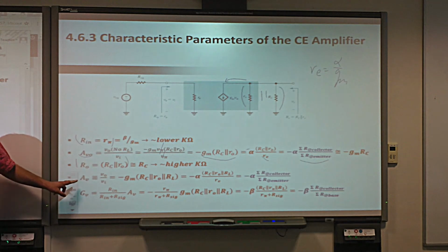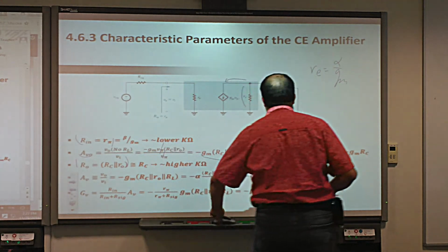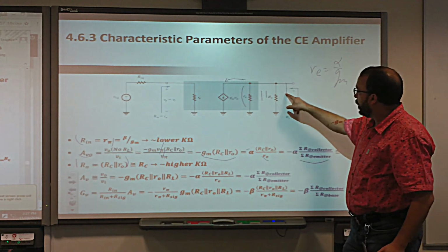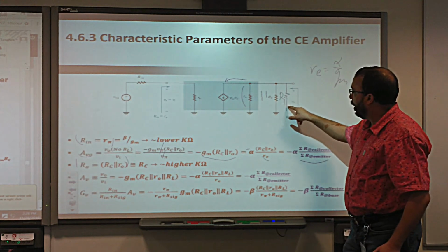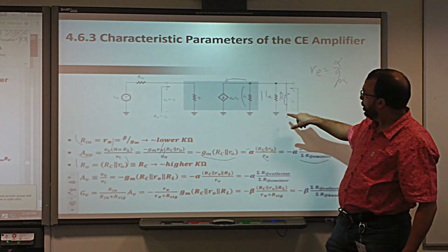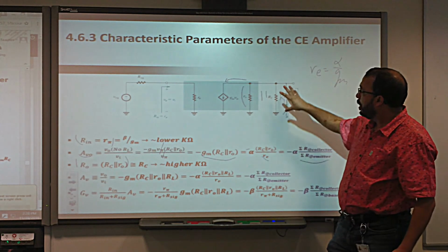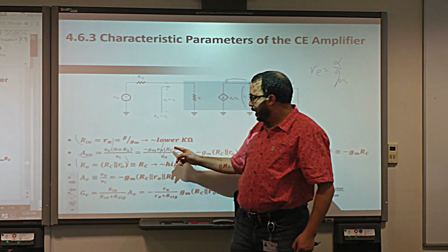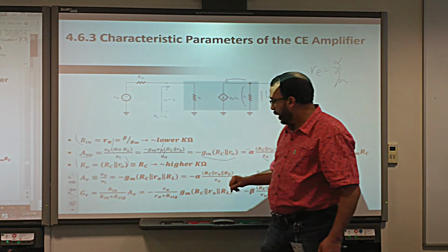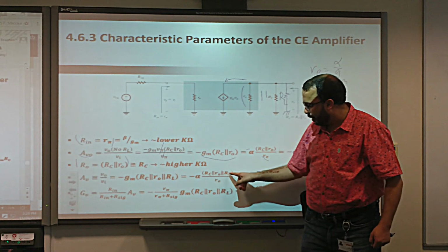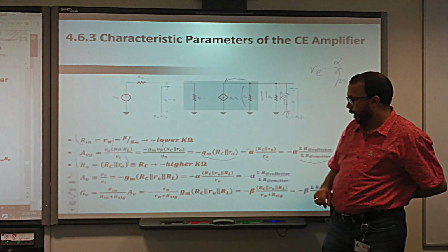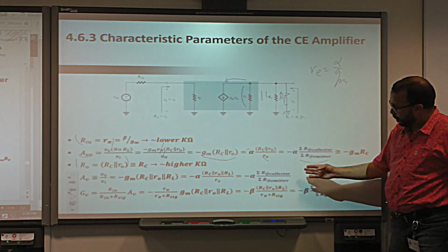Now, for the voltage gain, that means RL is included. The same thing, and it's very easy to calculate it, actually, because here, instead of RC, I will have RC also in parallel with RL, because the load is at the collector, okay? So here I have another resistor. So in that case, all I need to do is use Avo, and instead of RC, I just replace it with RC parallel with RL. That's it. Same, absolutely same formula, okay? And again, the same constant.